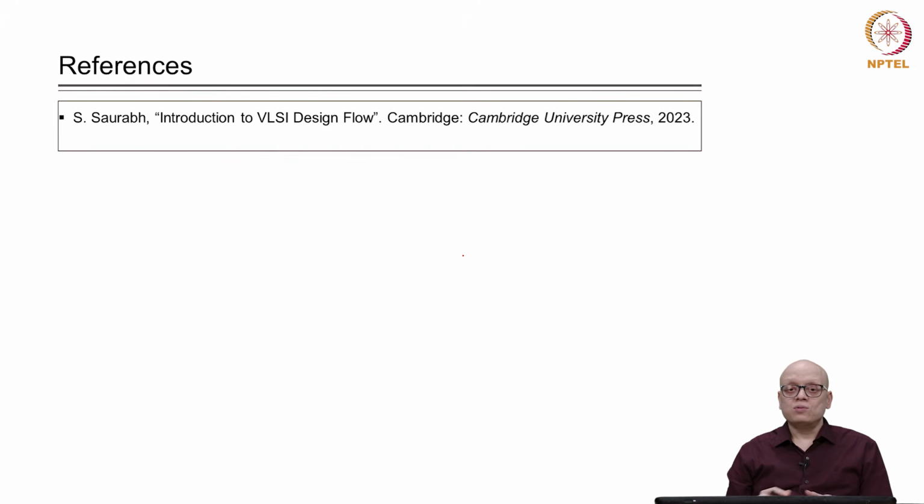Now, to summarize, in this lecture we have looked into why STA is needed in a design, and how STA ensures that synchronous behavior is maintained in a design by analyzing the cases for zero clocking and double clocking and throwing violations whenever it finds that there can be a situation of zero clocking or double clocking in our design.